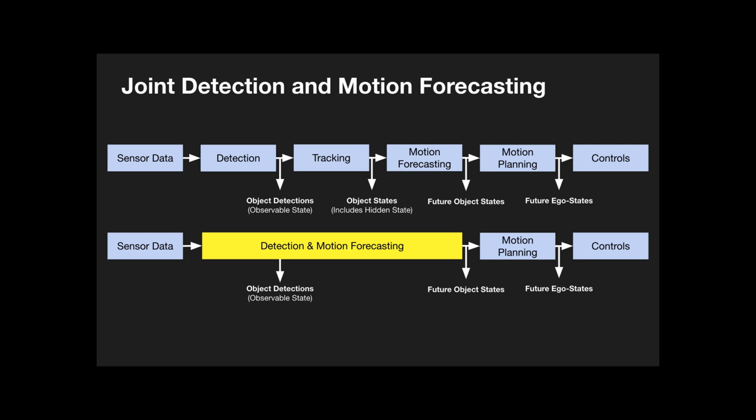Because I'm also doing joint detection, tracking and forecasting in my own research, it's really close. So I'm just wondering, even in your current pipeline of joint detection and motion forecasting, what about if the detection fails, right? You have a false negative, then you still cannot forecast it very well, right? So that means you still have this cascaded error here, even if it's trained jointly. You have end-to-end training, joint optimization, a joint cost function, but if the detection in the real world fails at inference time, you still cannot forecast it. I agree.